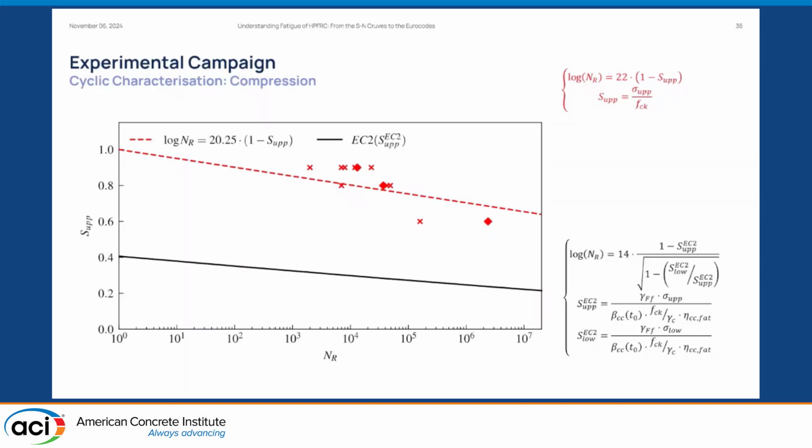Okay, this formula can seem quite complex, but actually it's not very different from the one above, except that we have a term at the denominator taking into account also the ratio between the upper and lower load level, and the load level definitions that are adopted in the Eurocode. In the Eurocode, you will find a particular parameter, which is fcd,fat, the characteristic compressive strength in design for fatigue.